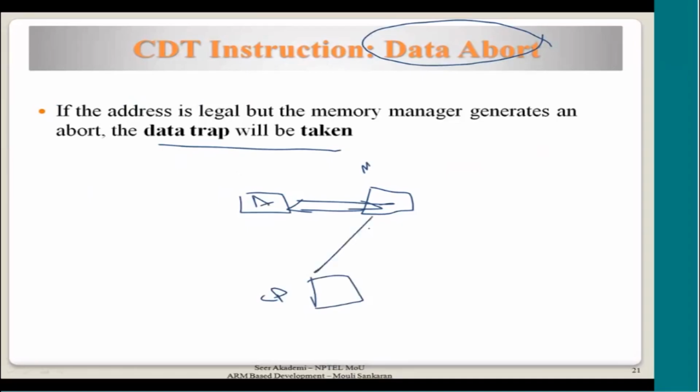The transfer may be between these two, but abort should be allowed because it may be that the floating point data is currently not available in memory. Then an abort has to be generated. Now who will execute the abort handler? ARM will execute it, not this guy. ARM will execute the abort handler, and then perform the job required for avoiding that abort, and then restart the instruction.